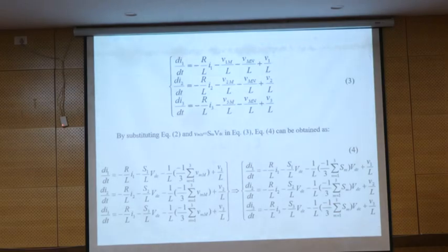Good. When you make the simulation, you never reach this point because we normally go through the dynamic model and provide the duty cycle. But basically, you should understand that S1, S2, S3 in this equation are the switching state functions in leg 1, leg 2, leg 3.